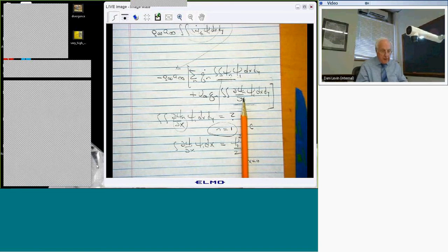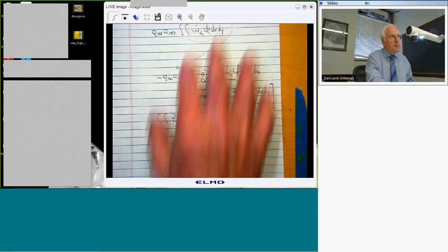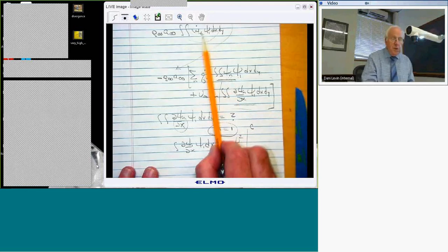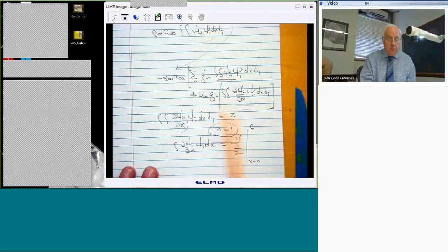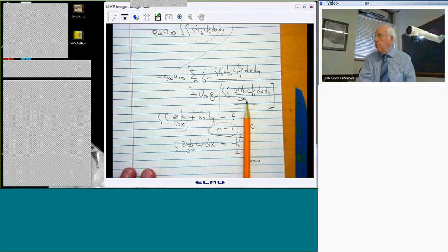So there are some things that you can anticipate. Of course, I'm relying on the fact that I've done a few of these calculations in the past, but if you look at the equations, they can tell you something about which mode is likely to be most important in terms of the gust input, which mode is likely to be most important in terms of generating damping, which mode is likely to be most important in terms of generating flutter.